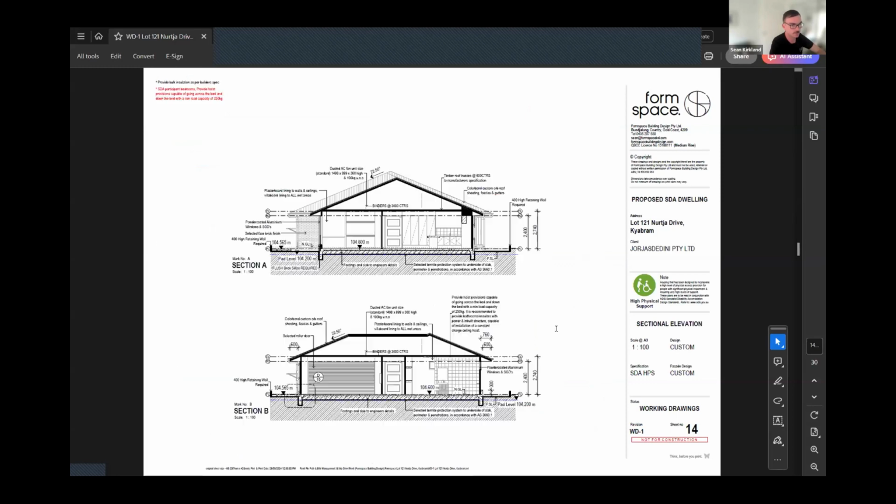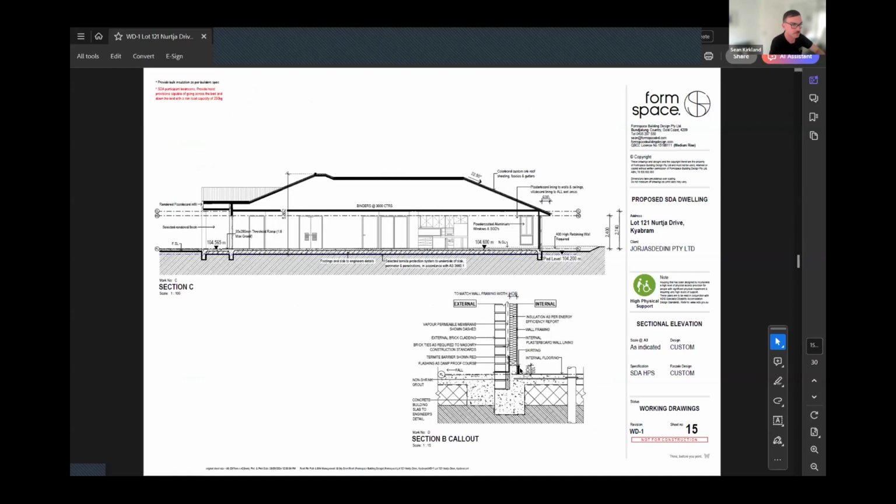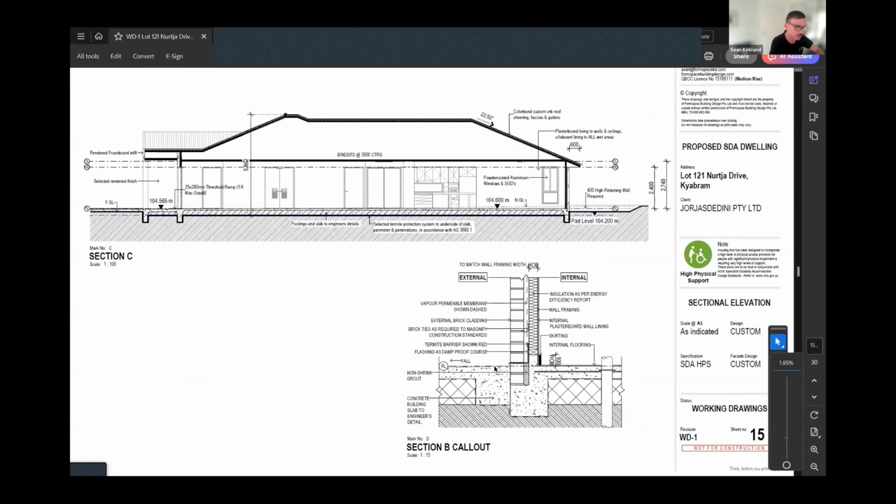So an example of this is on this slab plan, where we've nominated the hobs for the brick veneer. This is to ensure compliance with zero threshold ramping, DPC, visual, etc.